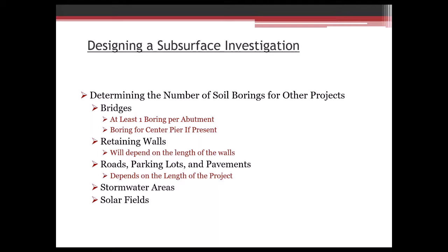Retaining walls is another area that we do a lot of borings for, and it's tough to give you guidance on the number of borings for retaining walls. A lot of it depends on the lengths of the wall, the heights of the wall, and a lot of different factors. So if you have those types of projects, it's very good to discuss it with the geotech engineer so that they have enough borings to feel comfortable with the design of what's going to be done.